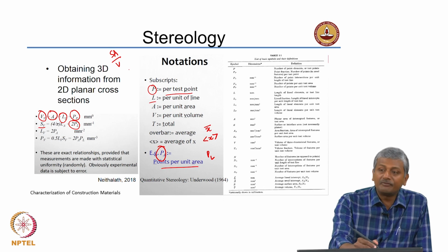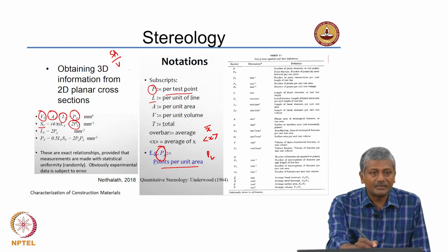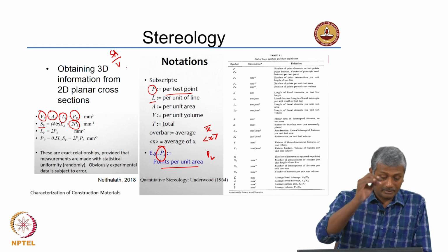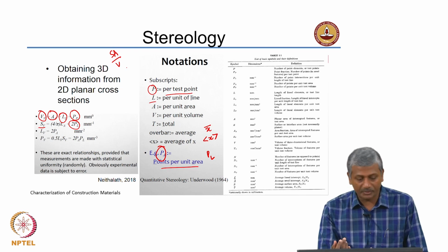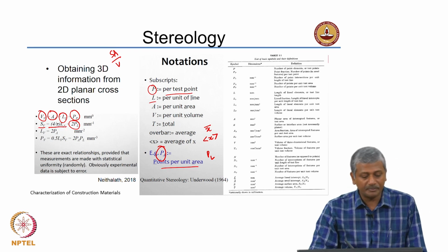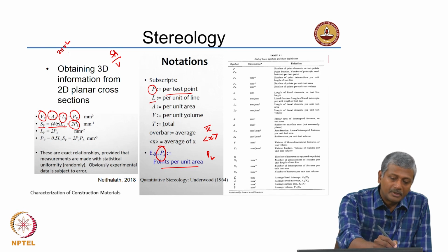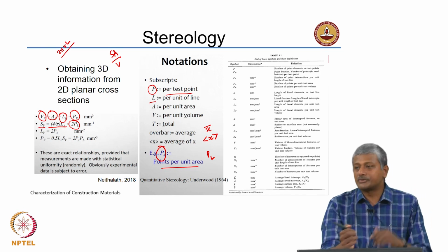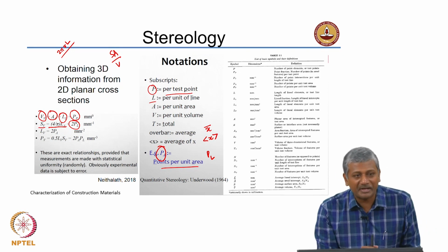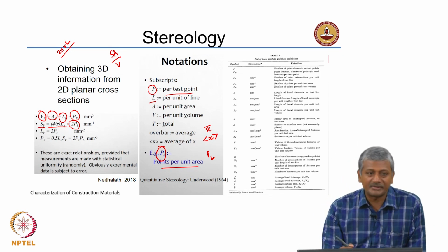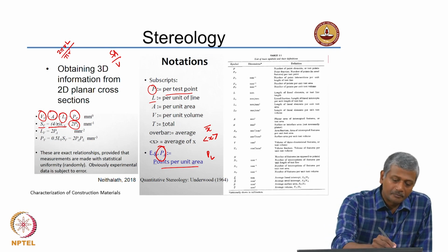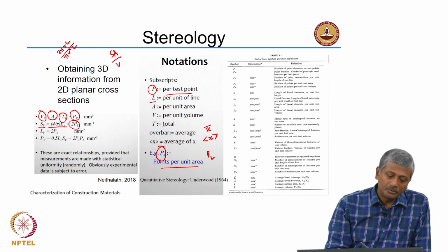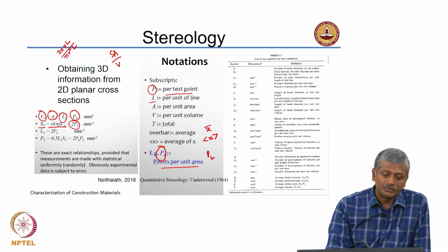Assuming that we have spherical or cylindrical phases, you can actually have different sorts of surface area to volume relationships. So, this is obviously for what type of relationship? It is 2 pi r L, of course, if the bottom and top are closed then plus pi r squared, but here we are assuming that it is an open pore, for instance, divided by what is the volume? Pi r squared L. So, what does this give you? 2 by r. So, what is this now?